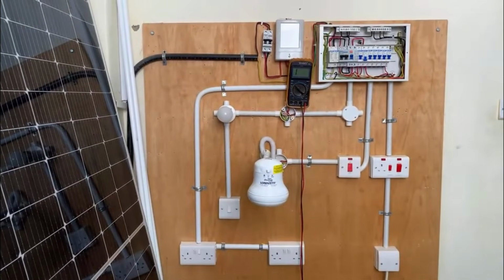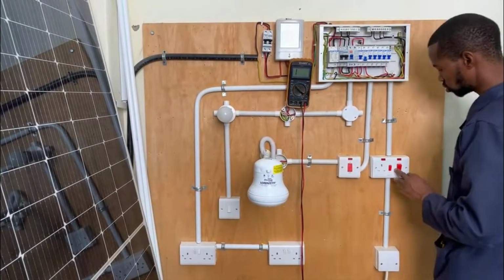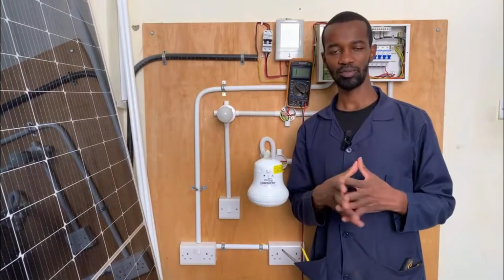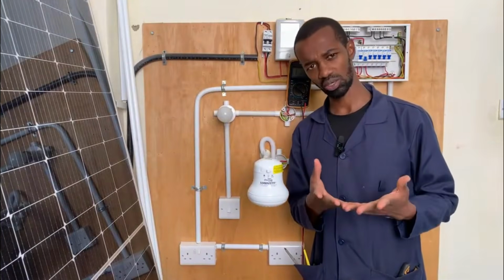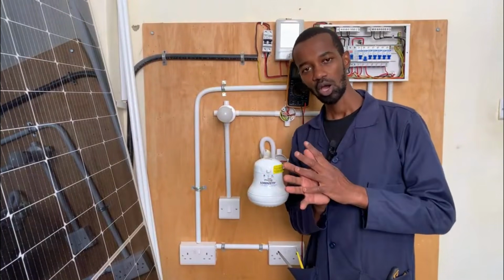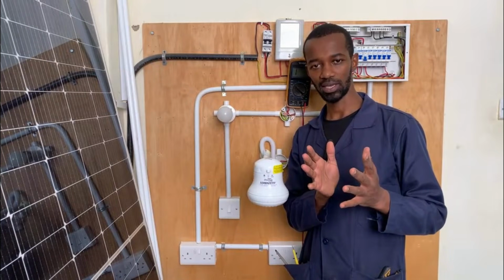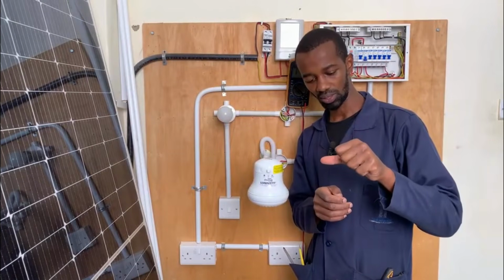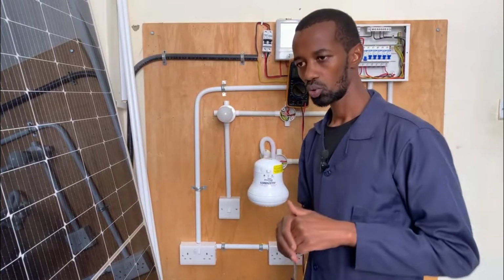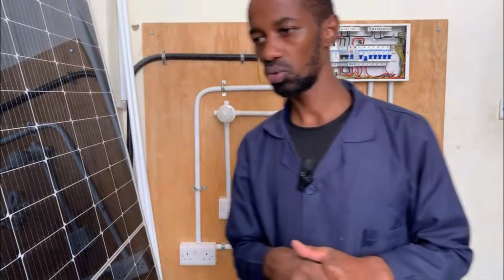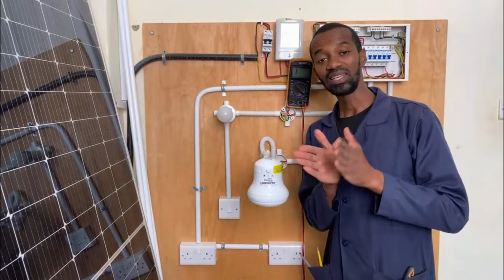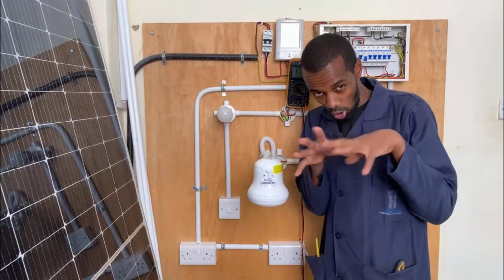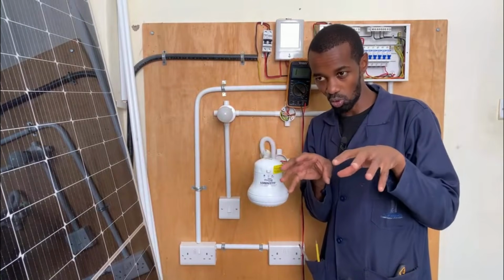So for instance, here you have a scenario whereby the cooker unit is on and the customer has said, my cooker is not working, it's not powering on. Those are some of the questions that you ask. Is it powering on? Is it only the hot plate, or even the baking section, the oven, or both? What about the lighter, the one that normally sparks to allow the gas to light up? You ask them, is it the hot plate? If they say it's the hot plate only, or one section of the cooker, then you know that the problem is localized in the cooker itself, the electric cooker or the electric oven.